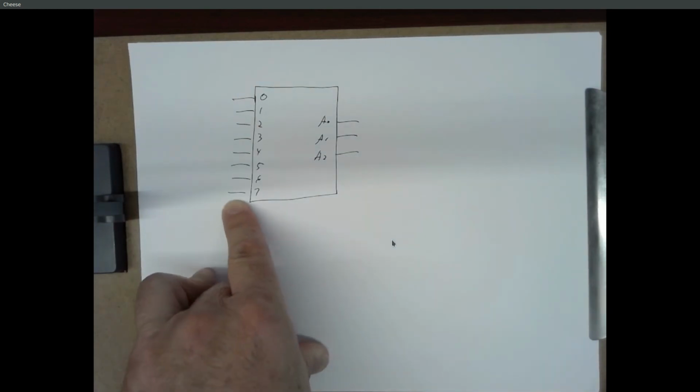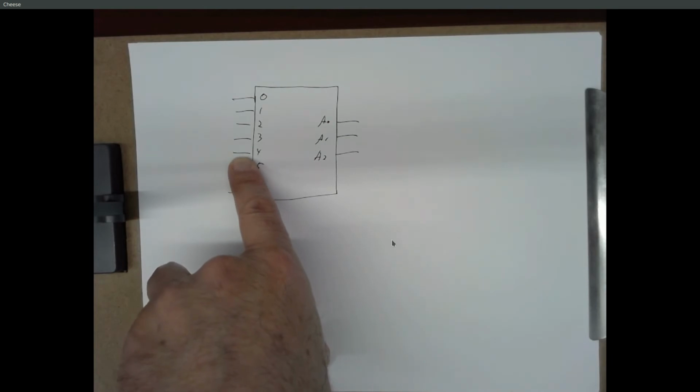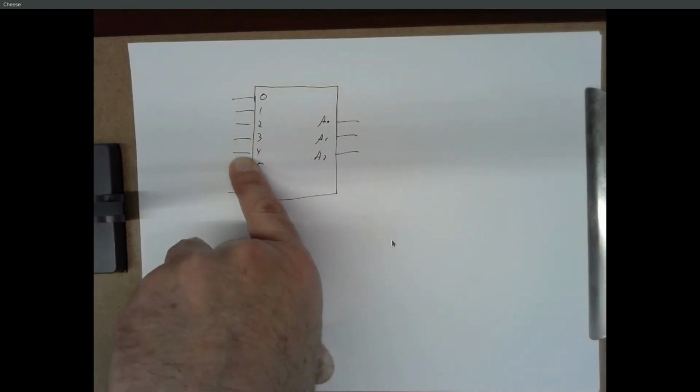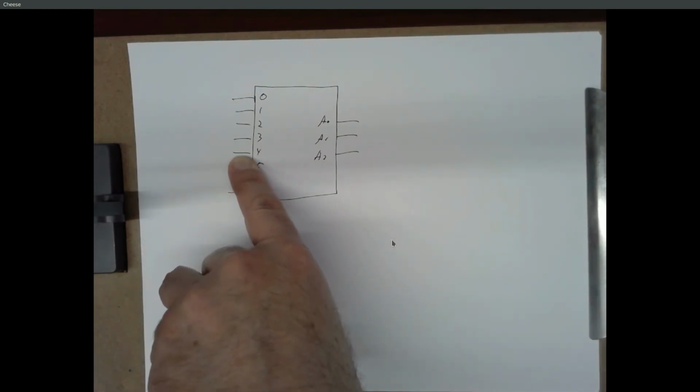This 7th one down here might say the CPU is on fire. Okay, it's a much more important event. This 4th one might say we've got a packet of information coming in from the network connector. That's more critical than somebody pressing a key on the keyboard, because by the time the person hits the next key, you're going to have gotten a lot of data through the network connection. It's a much faster source. So when something arrives on there, you've got to deal with it pretty quickly.